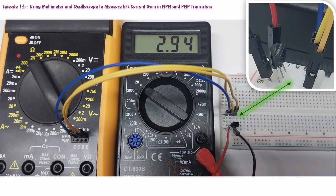Next task is to measure the base current. In order to do so, we need to rearrange our breadboard layout to accommodate multimeter probes, and put them between the source of base current from the hFE port and the base terminal of the transistor. Let's do this. This is our new setup.